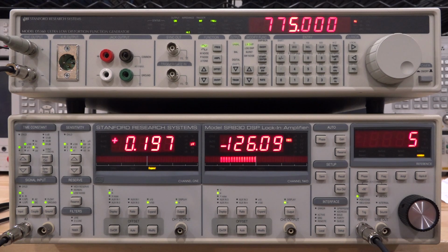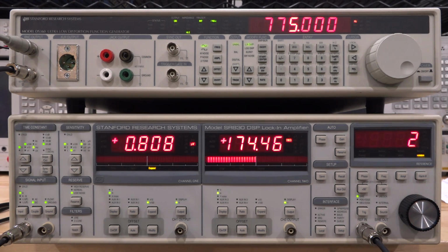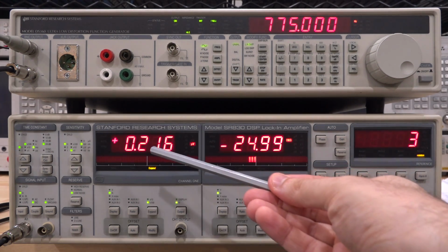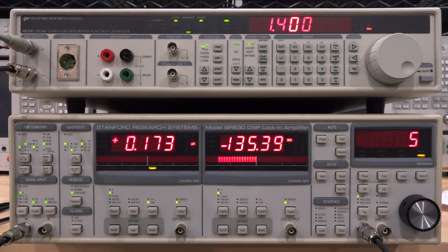Okay, so the significant one, the biggest one, is our second harmonic, and it's going to be the most significant also because it's the one that we need to amplify by 9 dB to counter the effect of the filter too. So what is the total THD based on that? Well, what I'm going to do is take this number, amplify by 9 dB, take the third harmonic power, this one, amplify it by 5 dB, and so on with the different numbers of the filter, and if you scale them and add them together, you get 2.6 microvolt RMS, and that's the total amount of power there. So let's calculate to see what our THD is.